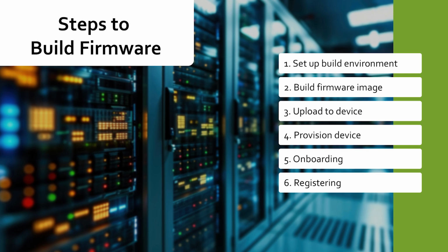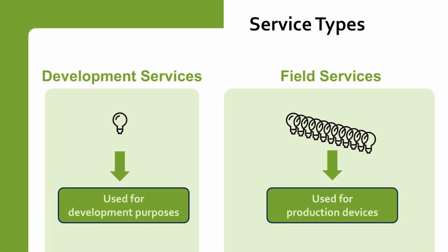In this tutorial, we'll cover the following steps: setting up the Ayla build environment, building the firmware image, uploading it to the device, provisioning the device, and finally, onboarding and registering the device. Testing new device firmware should be performed on devices connected to the Ayla development service rather than the field service.